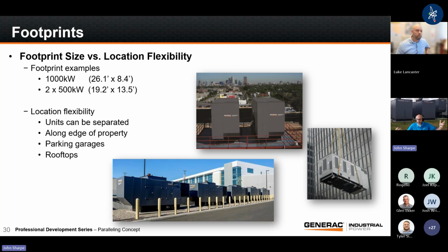A 300 kW gas generator is what that had. Total weight on that system is probably maybe 30,000 pounds for those 3 units, whereas a single 1,000 kW gas unit is over 50,000 pounds. Right, so I got a weight, I got a space, I got a dimensional conversation, and you've got a lot of flexibility when you start talking about integrated paralleling because you can move these units all over the place, right?